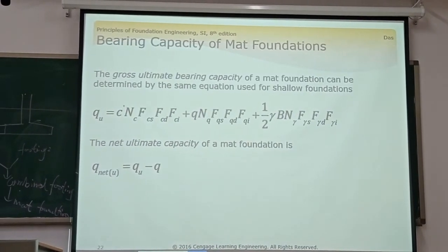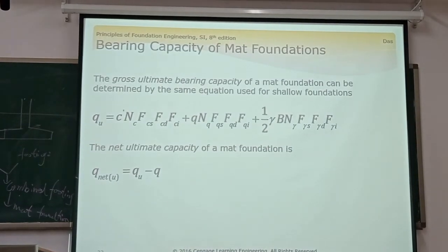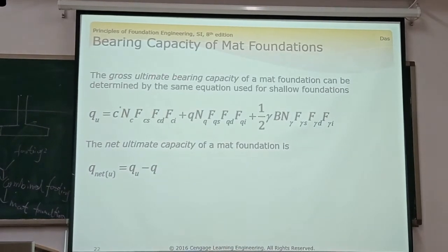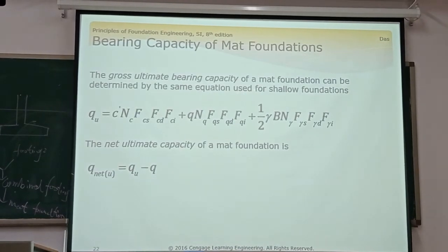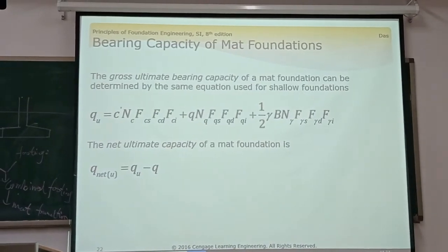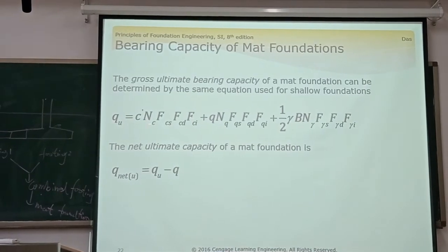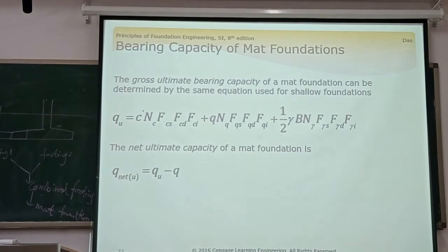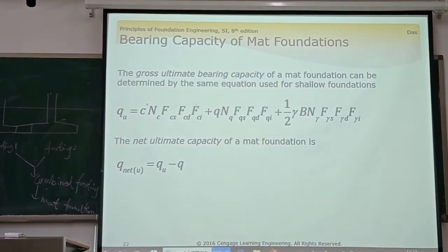When you design the foundations, the first step is to determine the bearing capacity of the foundation. For the mat foundation, the gross ultimate bearing capacity can be determined by the same equation used for shallow foundations, like the Terzaghi equation or the Meyerhof equation. So you can see this equation is whose equation? This is Meyerhof's equation.